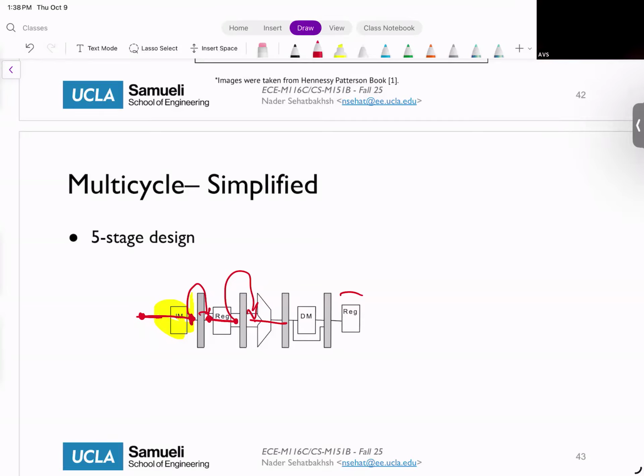If I didn't have the registers in between, it would have been all combinational, so it all moves forward, right? If I only had a register here and a register here, the clock comes, this value gets updated, and after some latency all the things get updated. But again, think about registers as your gates. Your gate is closed. It only gets updated when the clock comes. Then the next part of the system gets updated. Okay? Yeah.